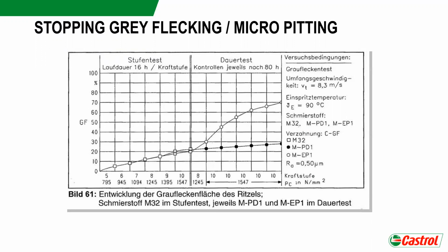One time to a high performing lubricant with conventional technology, so with, for example, phosphorus and sulfurous components in there, but with a high micro-pitting resistance on the data sheet. And the other time, in the other test rig, we have used a PD technology product instead. And what you can see is that even though you add a high micro-pitting resistance product with conventional technology, the damage progression still goes on.